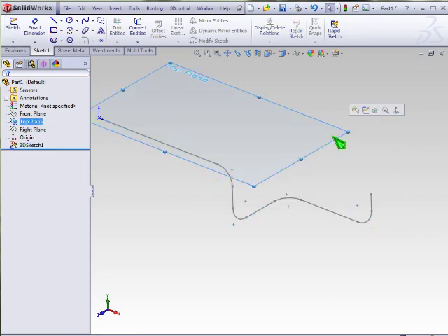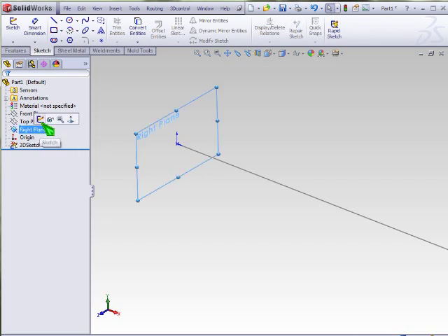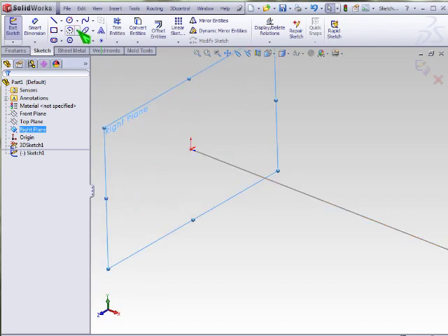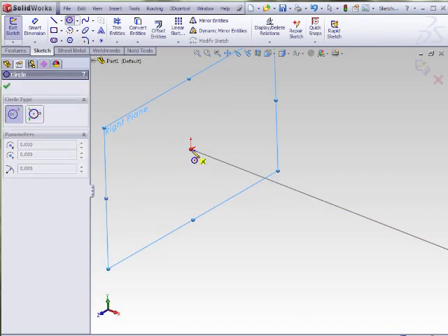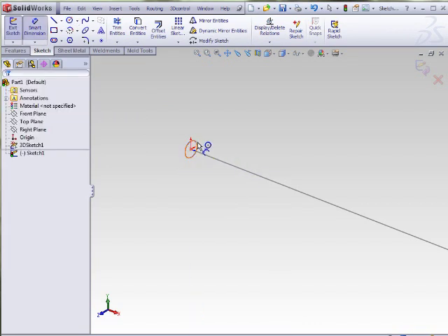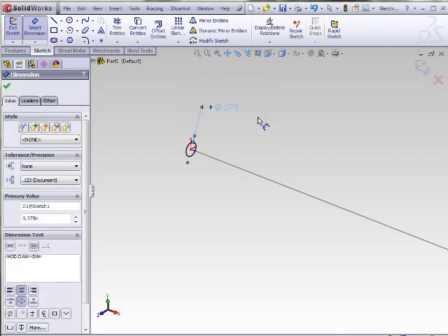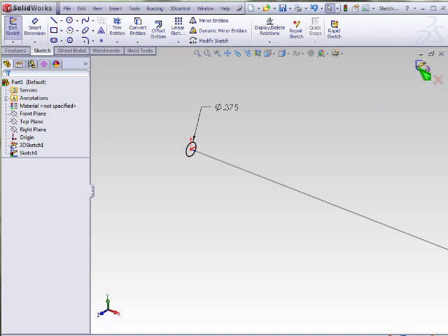Let's close out of that sketch and hide this plane, and then next we'll create the profile for our tube, and in my case it's going to be nothing more than a circle that will plop on the right plane. We'll wind up turning this into a thin feature, which is available when creating swept or lofted features. This particular tube is going to have a diameter of 3/8 of an inch. Make sure that you close out of your last sketch whenever you're creating a swept feature.